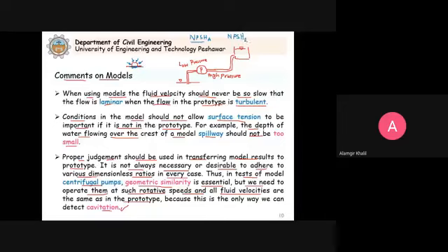So we have to make sure that when we select the proper pump, and also place and operate it in such a manner, this available net positive suction head is always greater than the net positive suction head required. So in that case, we can avoid this cavitation. I think the picture is available in your textbook. It is so enormous, it can even eat away the material.